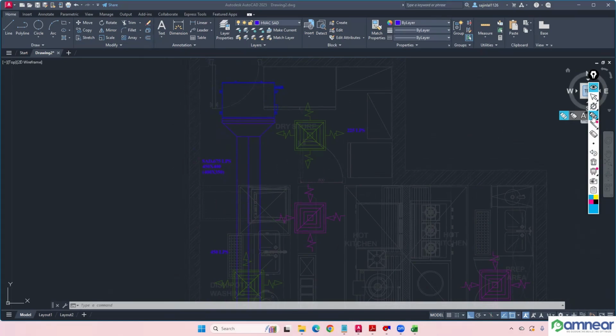Okay, but the plenum dimension we have to make slightly bigger now, because flexible duct with the plenum box we have to place. So this is my plenum box that will come above, and here I will be connecting the collar. From the duct side, it will be connecting to here. The minimum width we need 300, plenum box 300. Height we required, since the flexible duct diameter is 300, to accommodate this collar now for hammering elements and all, 300 plus 25 plus 25, 350 mm height we required. In the project session, we have already studied this one. So 350 mm height we required.